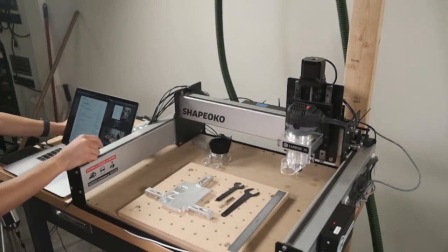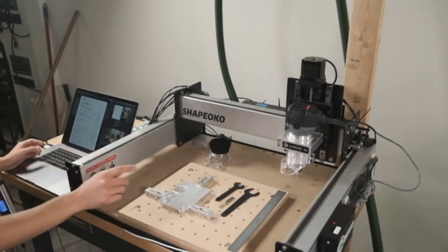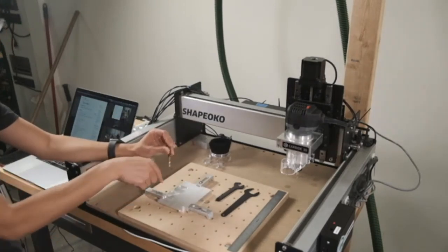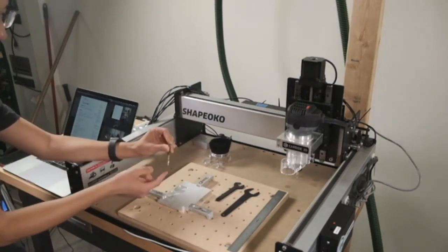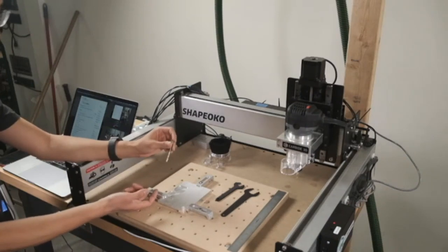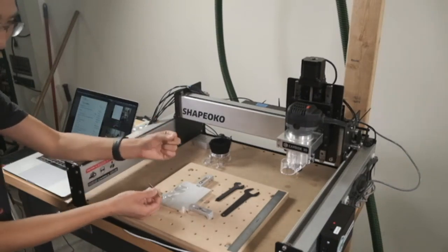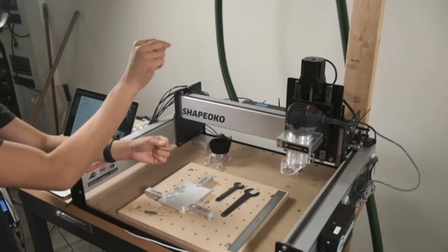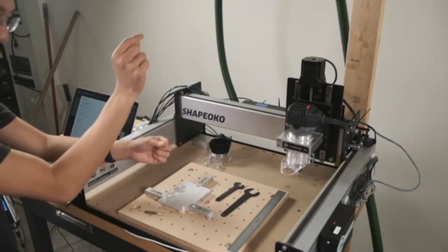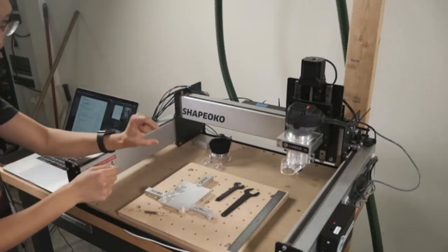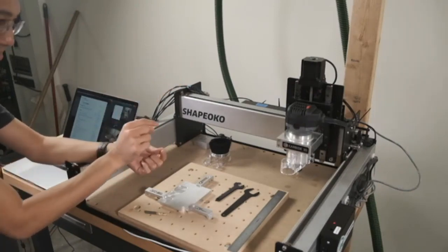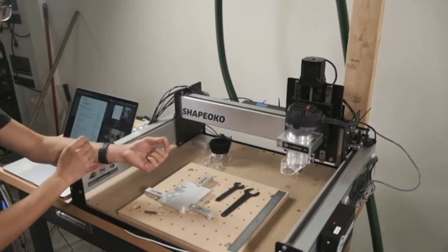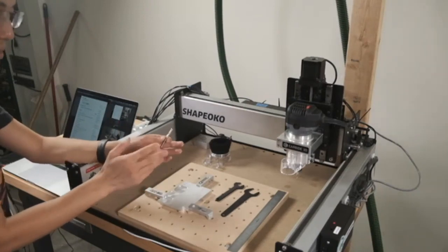And the thing to remember with those is that the longer an end mill is, the more it's going to be prone to vibrating, and the more fragile it's going to be. So if you imagine you're holding a very long piece of spaghetti, it doesn't take a lot of resistance at the tip to just snap that piece of spaghetti. But if you have like a 1-inch length, it actually holds up to a good bit of force. So the longer an end mill, it's a little more fragile.